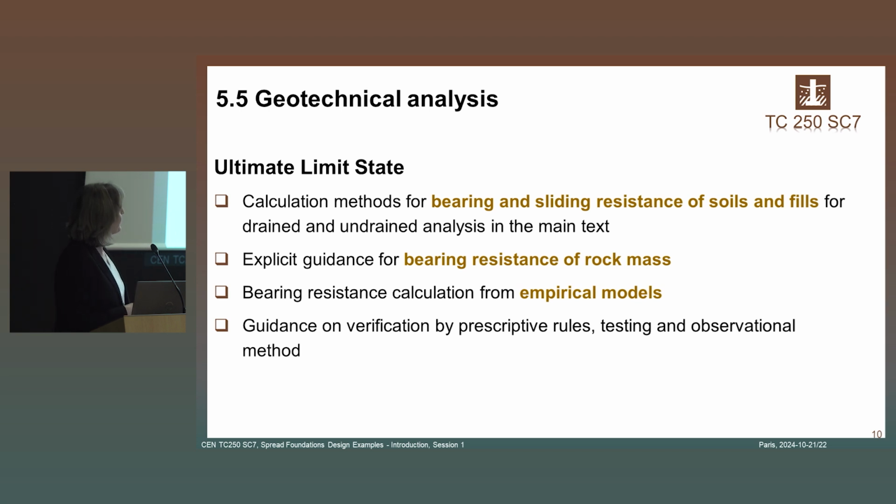So this has now been put into the main text for soils and fills, but there's also additional information on bearing resistance on rock mass and also on empirical models, because in some of the countries those methods are being used quite frequently. And there's also guidance on verification of prescriptive rules, testing, and the observational methods, which are the other types to evaluate limit states other than the partial factor method.